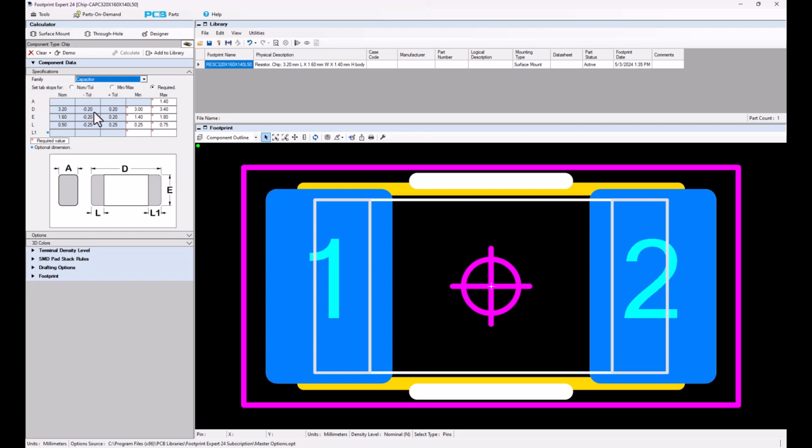And then once you get all those tolerances all laid out, I would recommend that you use just the nominal tolerances, because each manufacturer will give you a tolerance, but the tolerance is not locked in concrete, let's say. The tolerances are just there, and the tolerances are used to actually create the pad stack. So the bigger the tolerances, the bigger the pad stacks. The smaller the tolerances, the smaller the pad stacks. You should probably get all your vendors together and create one set of tolerances for each package size. 0402, 0603, 0805 will have their own package dimensions and their own package tolerances.